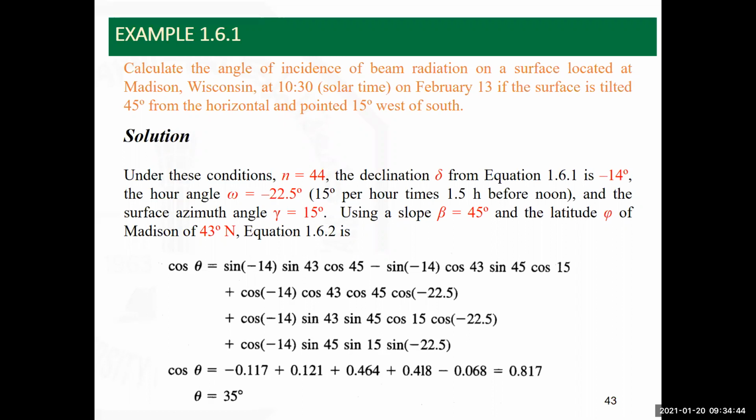When we talk about tracking, you have single-axis tracking, which follows the changes, for example, with the value of alpha, or it can be 2-axis tracking, so I can follow the change with alpha and with gamma as well, so that we get as much solar energy as possible falling onto the surface. That is the importance of knowing these angles and being acquainted with them.